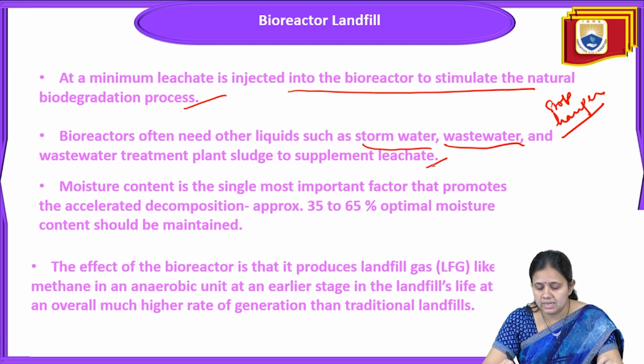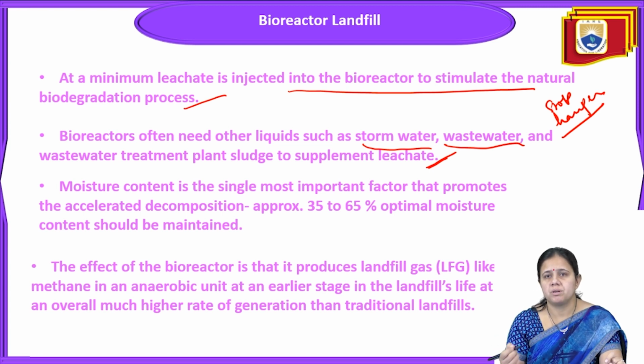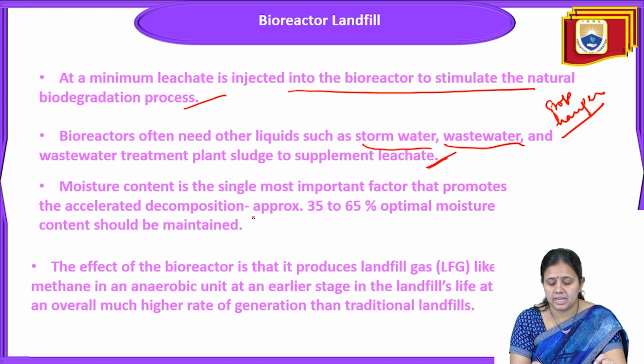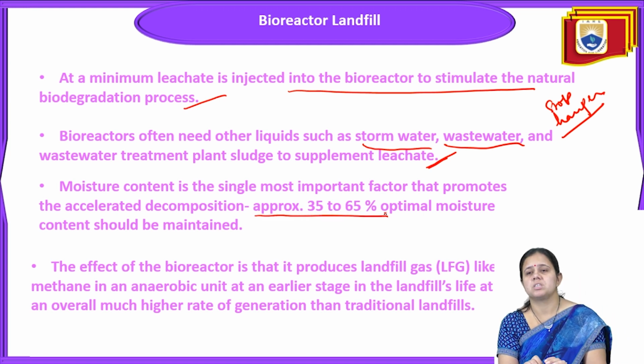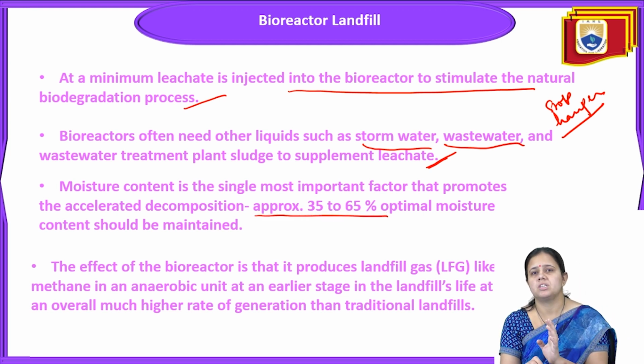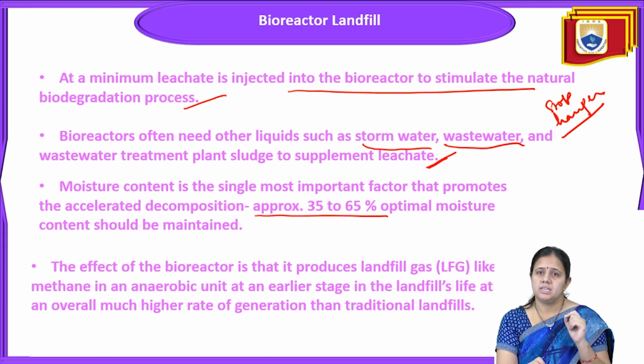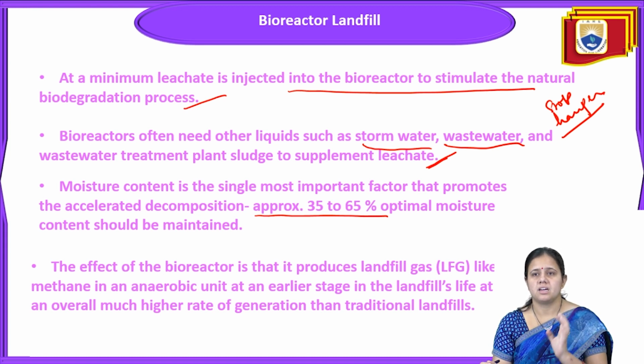Next, moisture content is the single most important factor promoting accelerated decomposition. Approximately 35 to 65% optimum moisture content should be maintained.